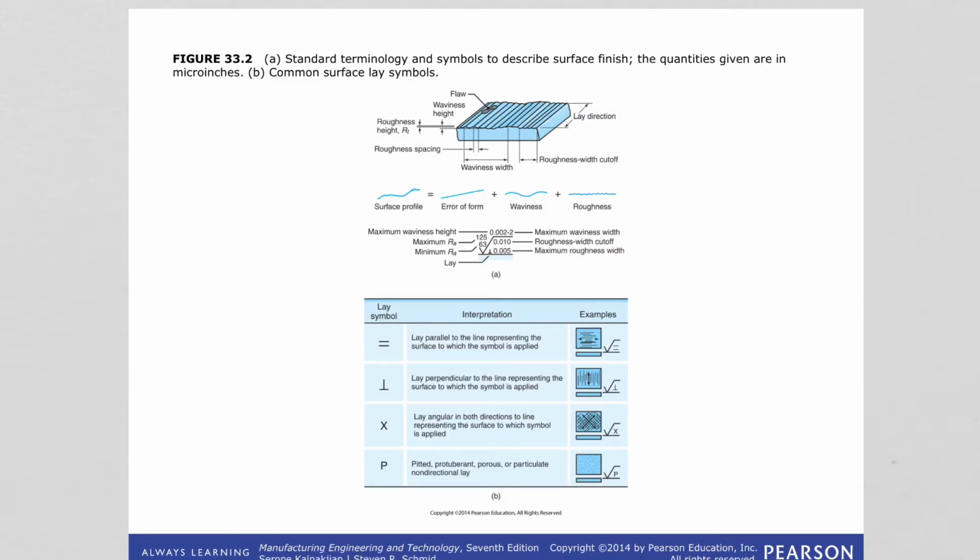So now we can visually see here and understand the terminology we have used to describe the surface texture. You see a flaw here, right? So right there, and we said this is just a defect, like scratch, crack, holes, depression, seams, whatever. There is the flaw. And remember, lay is the predominant surface pattern, the direction of it, right? We also call it directionality. So you can see the direction is right this. That is the lay direction.